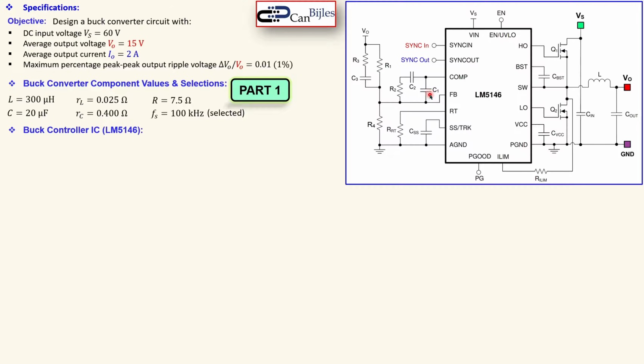You see here the capacitors C1, C2, and also resistors R1, R2, R3, and also R4. And this is the compensator, the type 3 compensator we actually have seen before. And that needs to be connected in this form, so the great details are given in the datasheet of this buck controller IC. You see also the output here, the input, and also our inductor and the capacitor,